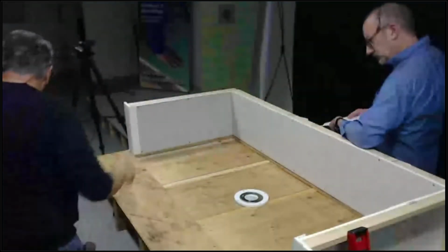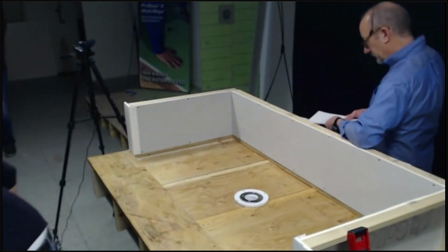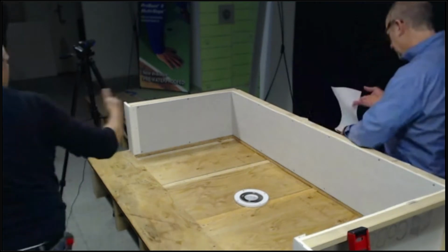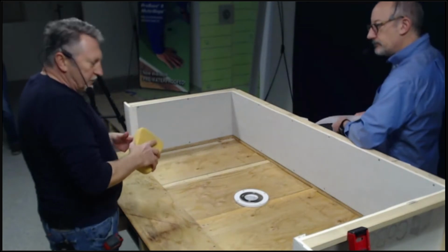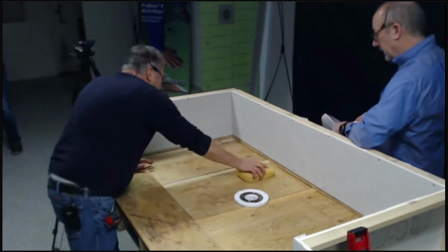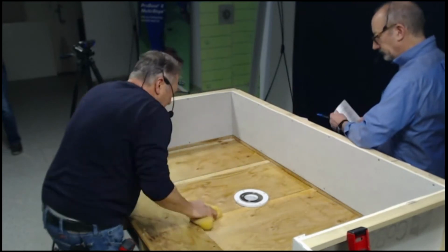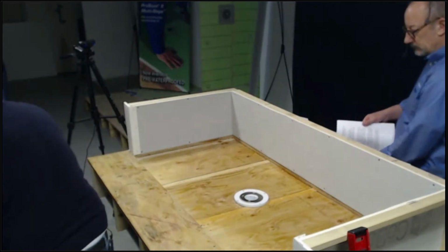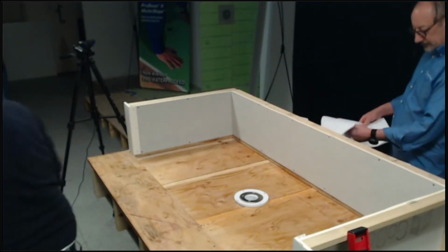So I'm going to use modified thin set, A118.4 modified thin set. Makes it a little bit wetter than normal, typically. Again, on any substrate, when you're using modified thin set, you want to worry that it's going to flash over on you. So I typically rub a little water on it, not too much, just so it doesn't flash over too fast. Get the dust off the substrate. Make sure it's clean.